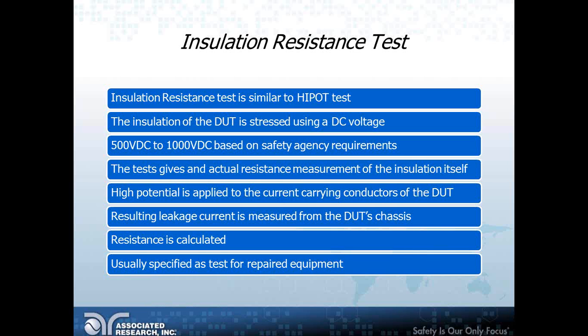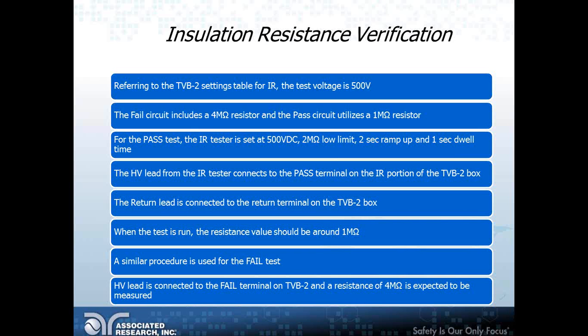So yeah, it's very similar in nature to the Hipot test, but gives some other important information. It gives out an actual reading for the resistance or the impedance of the insulation of the product being tested. Next, now that we know what the insulation resistance test is, how it can be run, and what information it provides the user, we're going to see if we can come up with a way of verifying whether our insulation resistance tester is working within specs.